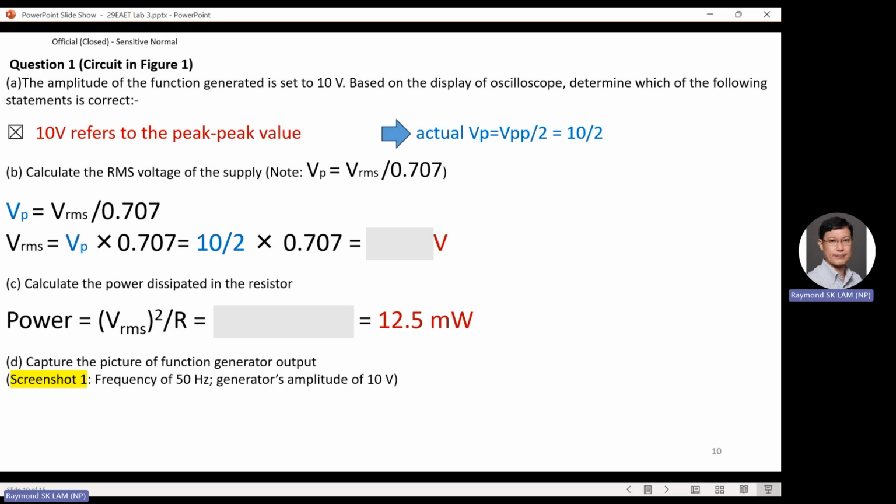And the next thing I want to highlight to you, when you see an AC source like that, and the question says the AC source is 110 at angle 0 degree, this value is always RMS. Okay, how to remember is RMS. The reason is it's very important to calculate power.